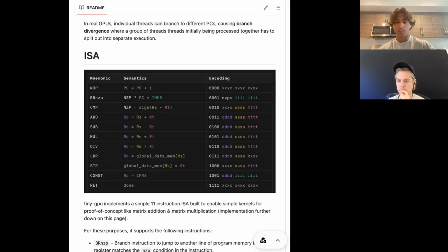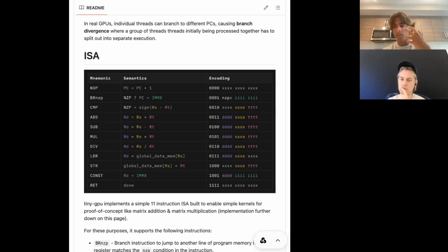And so these special registers are registers that you can't write to. The GPU itself handles writing to them. That means the GPU itself supplies this code execution environment with, hey, you're this block number. There are this many threads in each block, and you're also this thread number in this block. And again, that's how in the hardware, the code has access to those values. Now, the last 13 registers are read-write registers, which means the code is free to access and use them